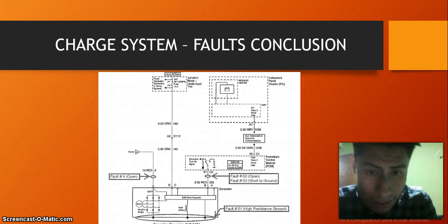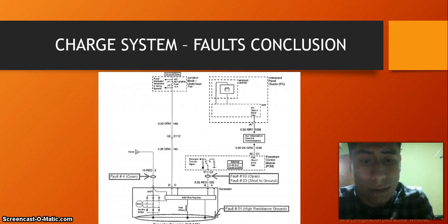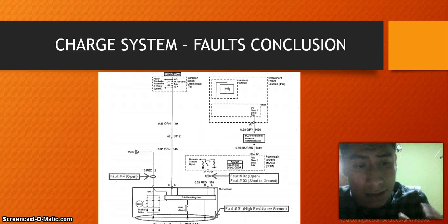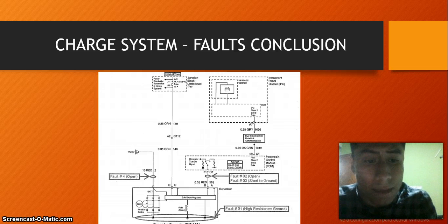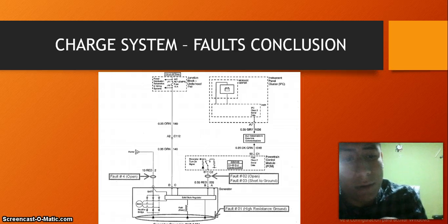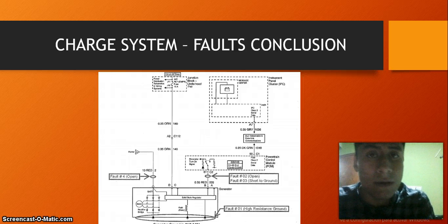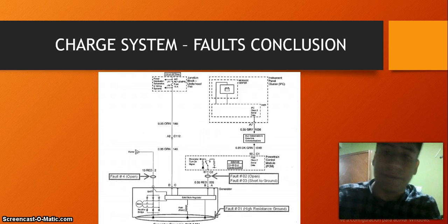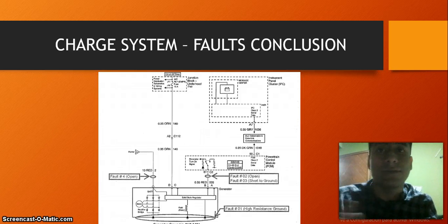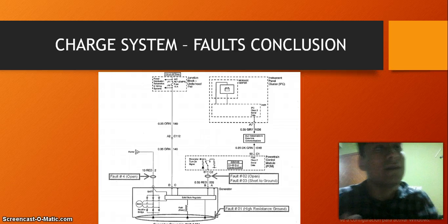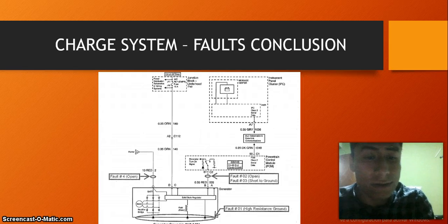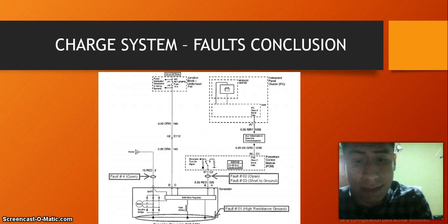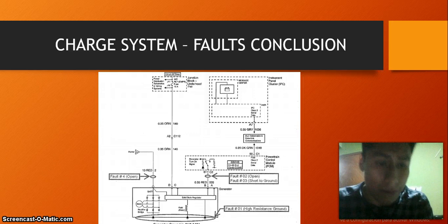Once the basic operating principle has been known, a fault was simulated in the system, so that it can be identified according to the analysis performed on the operation of the system. The failure was based on the fact that the battery was not recharged correctly. The current provided to the alternator is 12 V, but the alternator output is bad. This was determined because using the multimeter this fault was noted: the 14 VDC that were initially delivered to the battery.